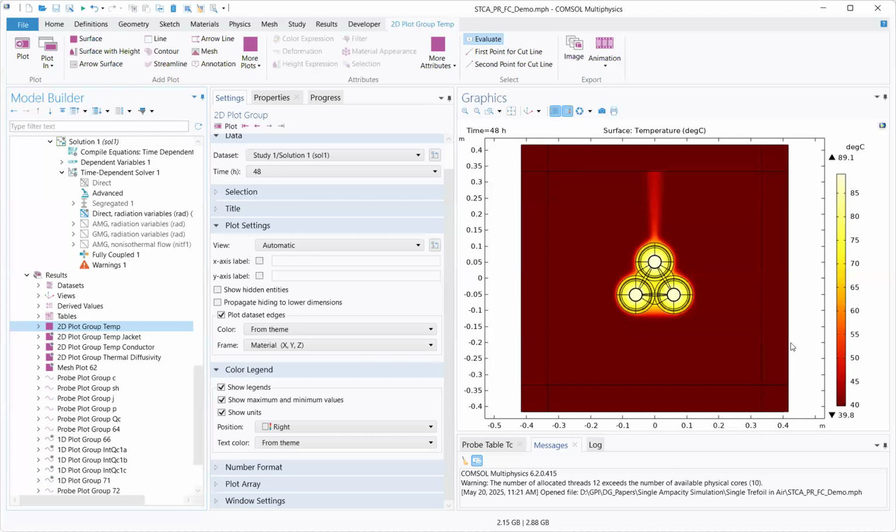If I see that I'm measuring a temperature that's lower than my minimum, then that's a problem. Then I would stop the simulation, and perhaps the airbox size needs to be bigger, or this infinite domain thickness needs to be bigger. Something needs to change, and increase the mesh density. This right here is showing that it's not respecting my boundary condition, right? Because that boundary condition needs to be respected.